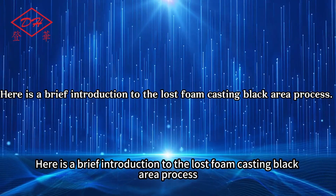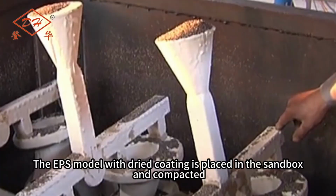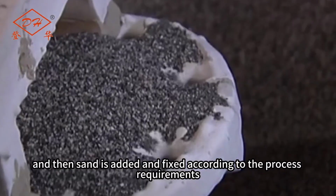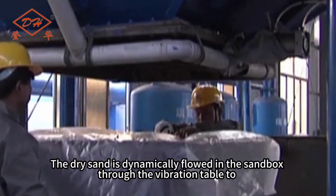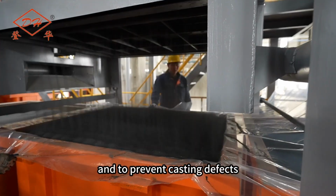Here is a brief introduction to the lost foam casting black area process. The EPS model with dried coating is placed in the sandbox and compacted, and then sand is added and fixed according to the process requirements. The dry sand is dynamically flowed in the sandbox through the vibration table to improve the compactness and density of the dry sand, and to prevent casting defects.